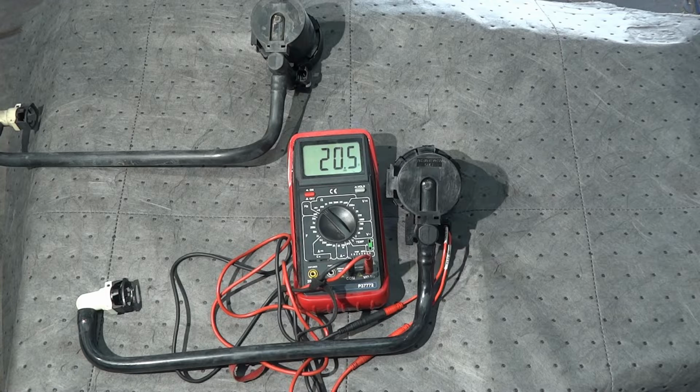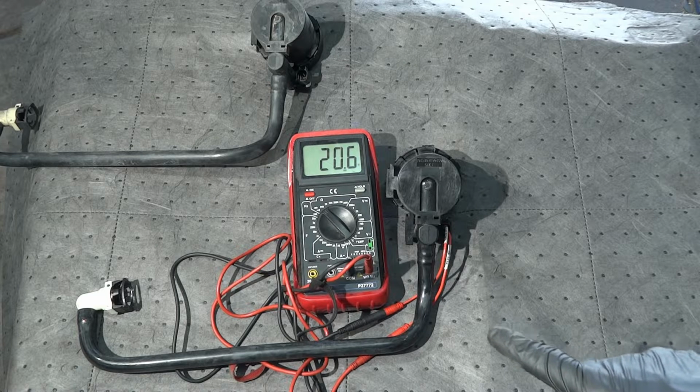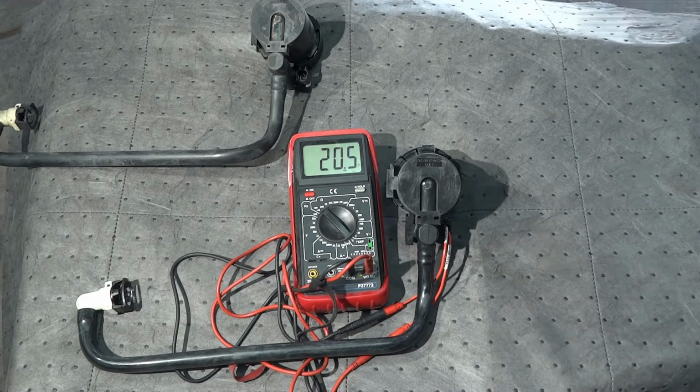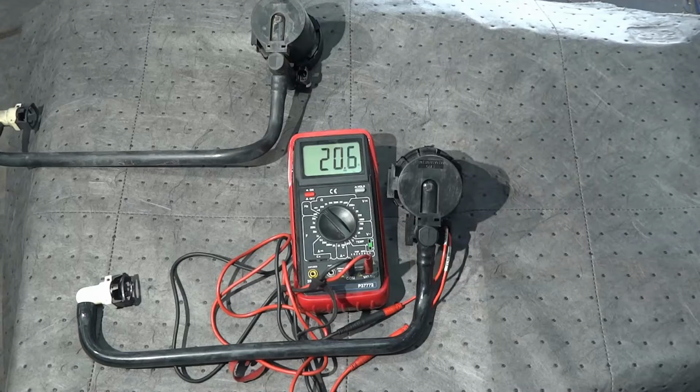So now what I need to do is I kind of want to do a continuity test on the harness that's on top of the fuel tank. I want to make sure that harness on the fuel tank is good, because there isn't a huge difference of resistance between these two solenoids. Let's do a continuity test on the harness of the fuel tank, because we might have an open between the main connector here and the connector at the charcoal canister. Let's check that, and if that's good, we're gonna install our new vent solenoid.